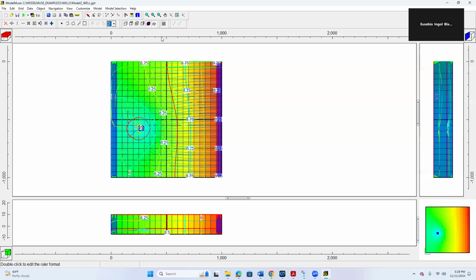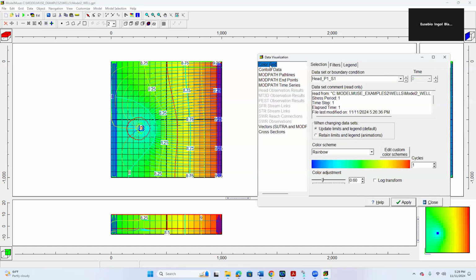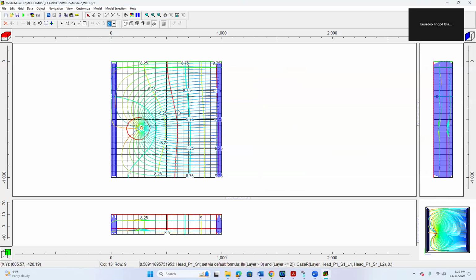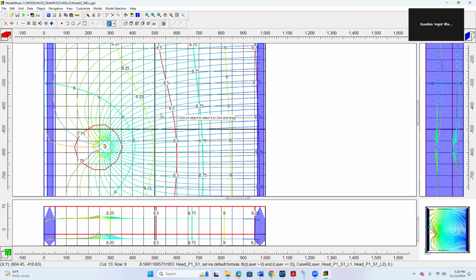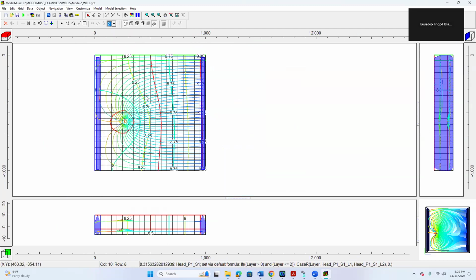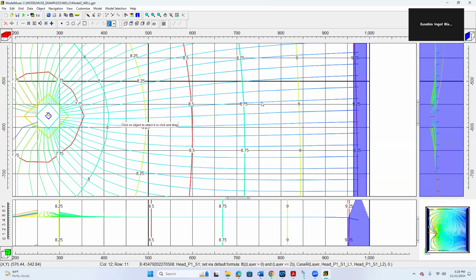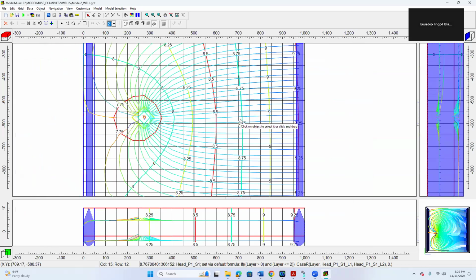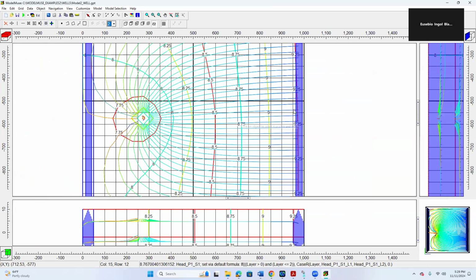And then we are going to unselect the grid here. We are going to put none, to see the path line better. Look at this. That one is the path line now, okay? That one was the path line. That one is the contour lines, and then you know the path line, okay? Remember, the stream lines and the potential, right? And the contour lines in this case, okay? Contour line. This is the groundwater levels, and then of course that one is the paths, okay? Then you are going to see it this way in your model, okay?